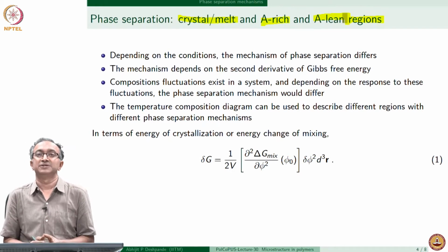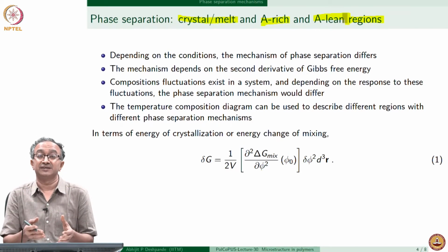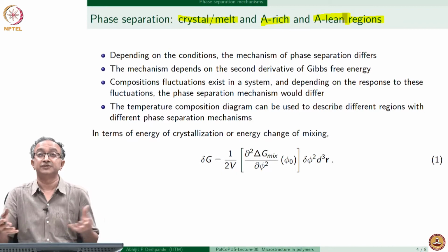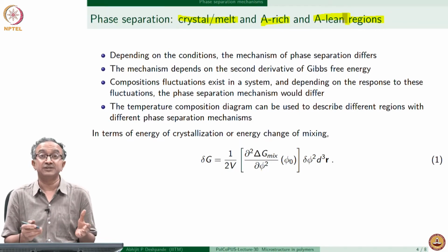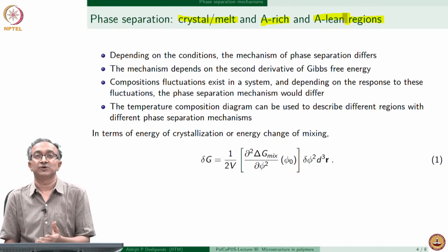But in the case of polymers, the final state is a glassy state, and therefore whatever the phase separation mechanism does to the distribution of macromolecules gets frozen there. So it depends a lot on how the phase separation was done.